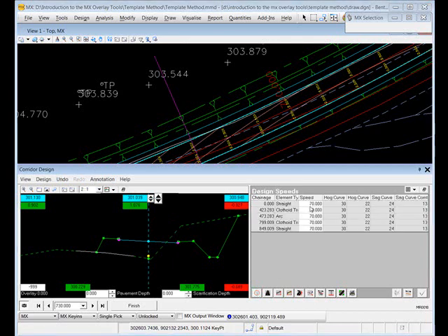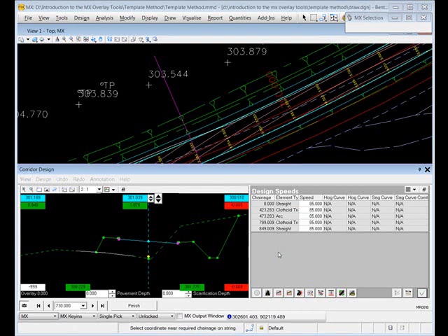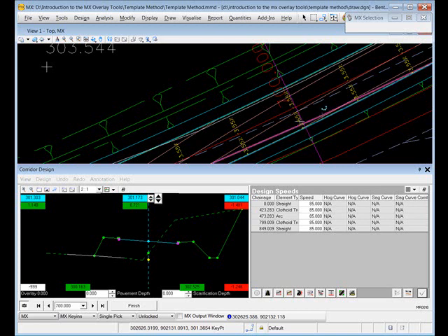But I'm going to make a change now to the design speed. In this example, I'm going to change the design speed over the whole length of the alignment, but I could do it over particular tangent point ranges if I wanted to. So let's just increase the design speed to 85 kilometers per hour. Click the refit button again, which reprocesses the whole design. And as you'll see in just a moment there, the plan graphics have updated. We can see the crossfalls have changed to 3.55%, so more super elevation on the higher speed.